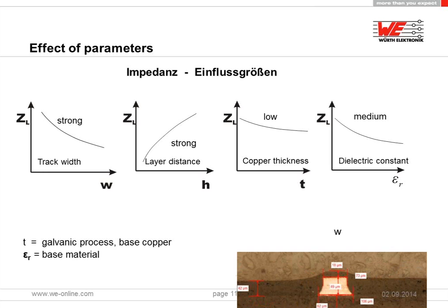Okay, thank you for your answers. So it's quite interesting. You could not decide really between thickness of flexible material polyimide or line width. Of course, you are right that the line width is very important and has a big effect on the impedance value, but as the question was asked, it's covering the specialty of flex rigid.